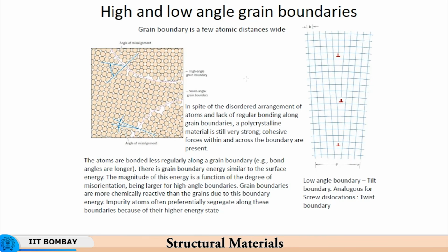When you anneal the material, meaning when you heat the material, again I am using terms which I have not defined yet, one can start with one kind of grain boundary and obtain another kind of grain boundary. So basically what I am trying to tell you is that through a certain set of manufacturing processes, constituting a manufacturing route essentially, you will be able to generate low angle grain boundaries, high angle grain boundaries, defects in specific planes, and orientation of crystals.